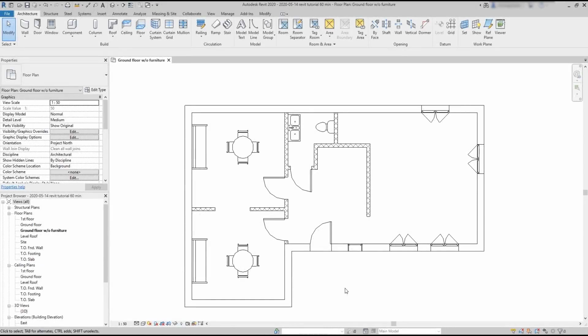Hierarchy terminology. Now let's talk a bit about the hierarchy of elements in Revit. It's important that we understand these concepts. Any element in Revit, for example, let's use as an example this window, falls into three hierarchy states: category, we mentioned it in the previous chapter, family and type.